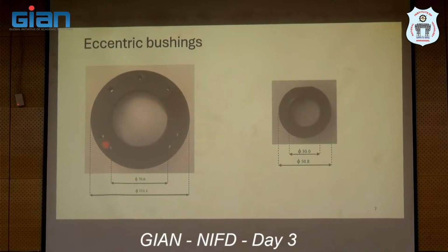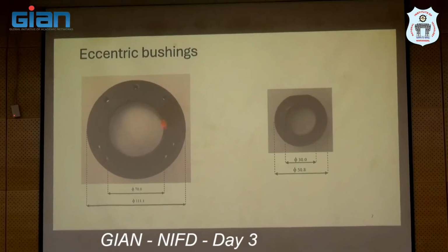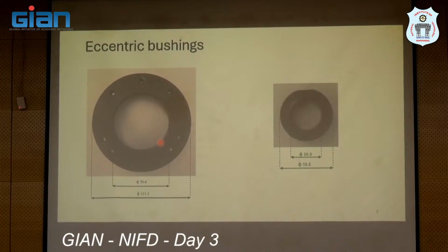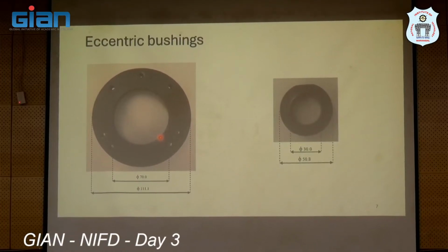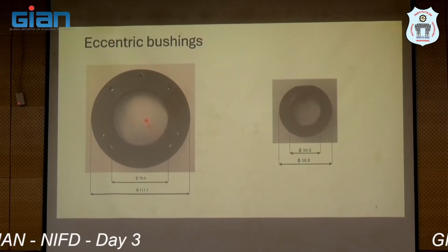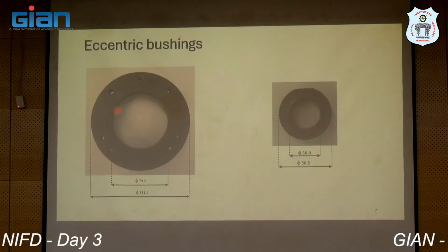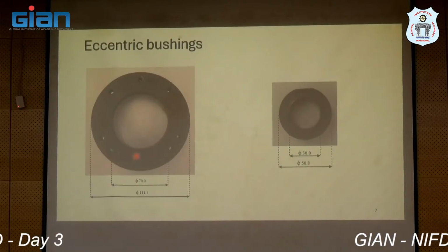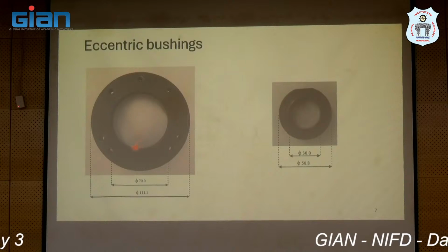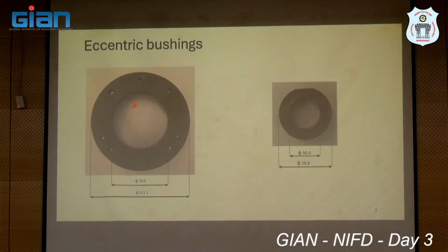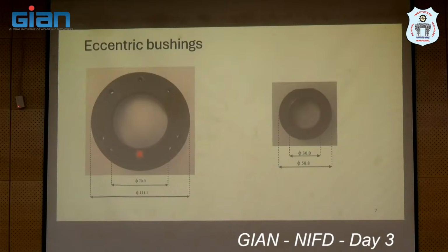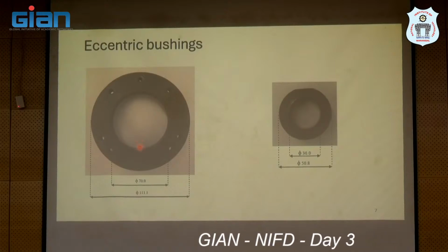And this bushing is what will help you level shift your shaft. So the bearing will go inside this groove, but what will happen is it's eccentrically displaced. That means on one side it has higher height than the other.